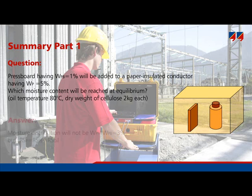It may be around 3%, because both the pressboard and paper are cellulose materials. However, it is not the moisture content which will become identical. The relative saturation inside the pressboard, in the paper, and also in the oil will become the same. It is important to note that the moisture content will be different, but the moisture saturation will be the same.